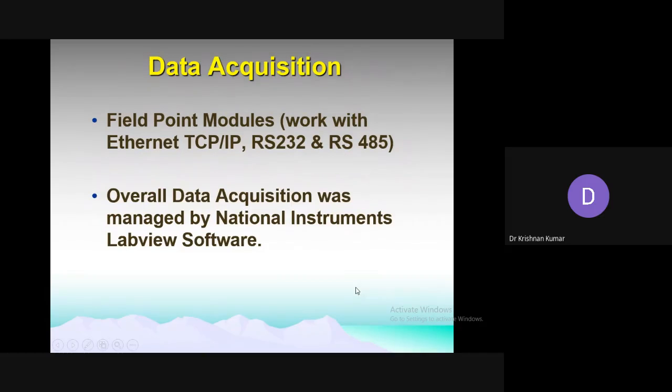Now for data acquisition, as I already told you, we have used the FieldPoint modules for the entire bridges. They were very rugged, even up to 17 years. One or two modules did not work in between, so we changed those modules, and even now it is still working.